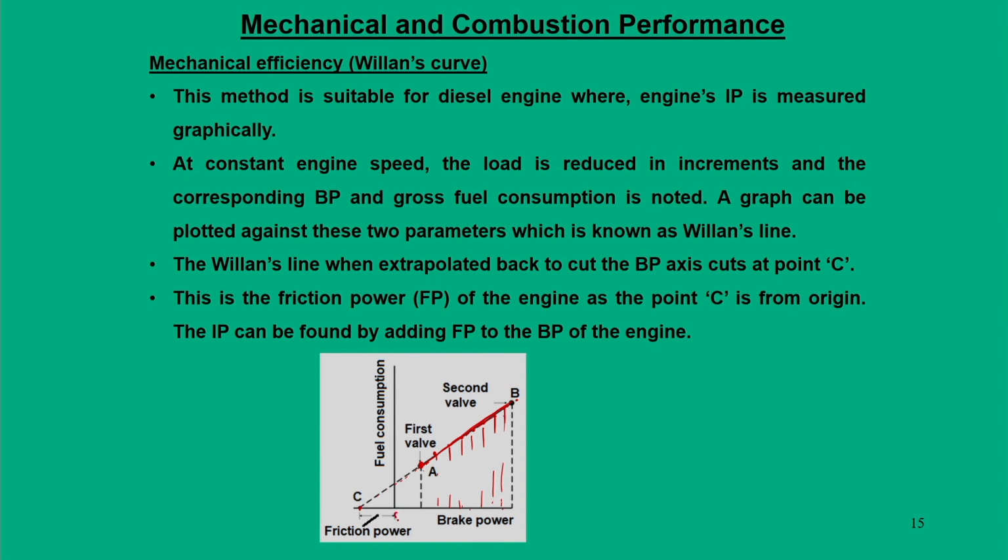If you take the origin as O, then OC can be considered as the friction power, because it is on the negative side of the power axis. In this fashion we get the friction power, and we also know the brake power. So, one can find the relation between them. From these two expressions we can find the mechanical efficiency, that is brake power divided by indicated power.